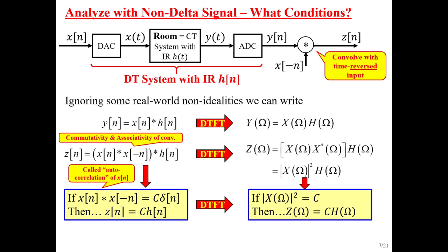Interesting. And we can also see this in the frequency domain. So remember, this turned into this, and so this will turn into just a constant. In other words, the signals that satisfy this are exactly those signals that have a flat constant DTFT or a flat spectrum.